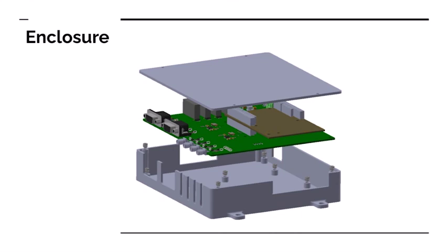Our system is intended to be mounted vertically to the outside of a concrete test site during use, and that can be done easily using 1/4 inch bolts, which will pass through the flanges on the top and bottom of the enclosure.